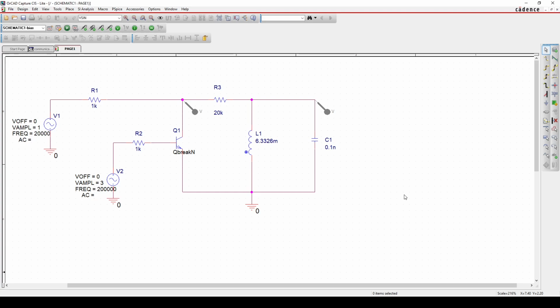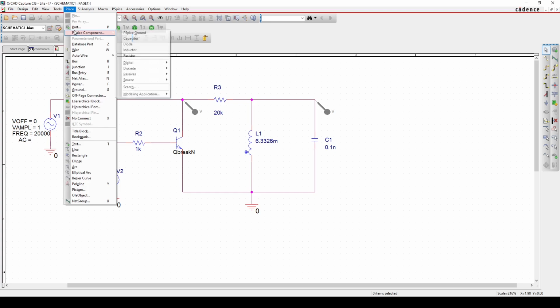This is the circuit to generate DSBSC using a switching modulator on ORCAD. All the components used in the circuit can be found by going to Place, PSpice component, and I used the resistor, inductor, and capacitor. And for the transistor, I went to discrete and got an NPN.